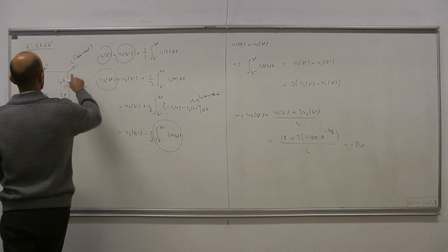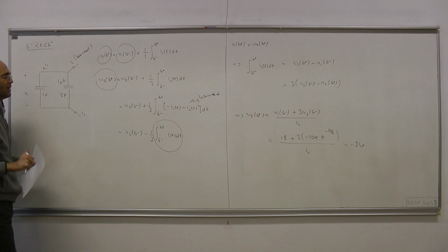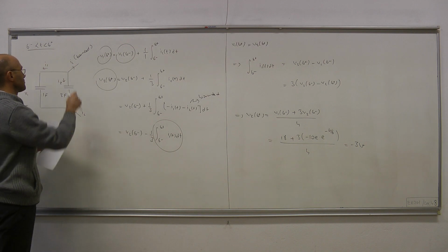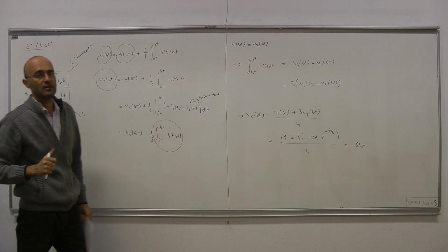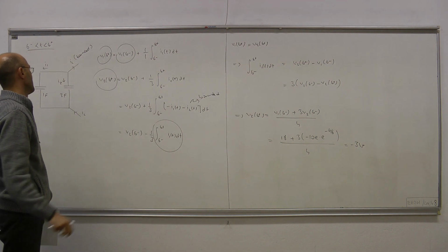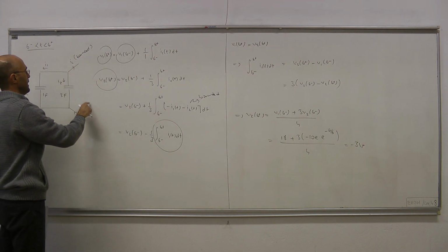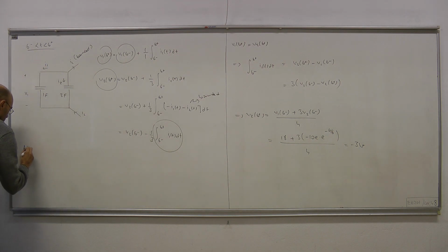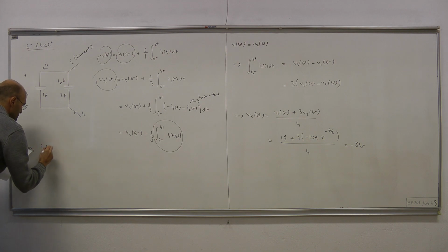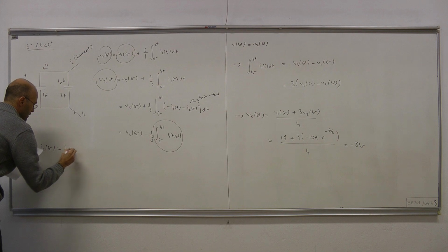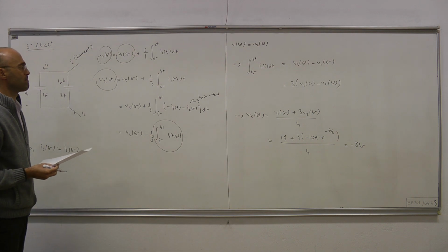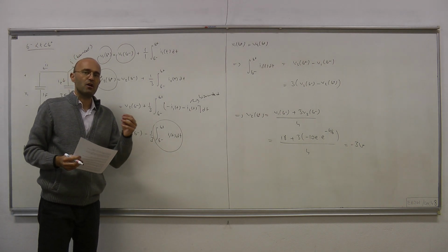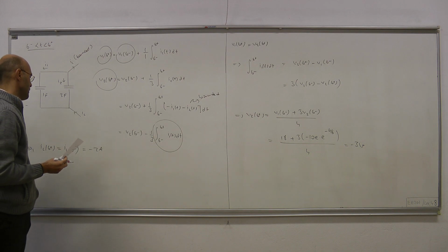We also have to figure out IL(6+). And IL(6+) is IL(6-) because the voltage of the inductor has to be bounded. Okay, so it makes a series RLC circuit with the capacitor and the resistor. Also, IL(6+) must equal IL(6-), and we know IL(6-) equals minus 2 A because IL was constant for times between 0 and 6 minus.